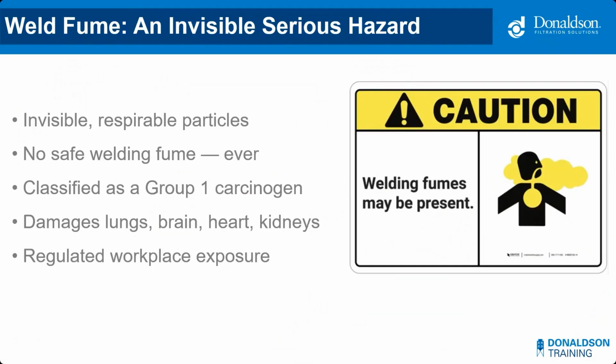Welding fume particles are extremely small, small enough to pass your body's natural defenses and lodge deep in the lungs. Because of that, there's no safe welding fume. Every arc, every process, every day creates hazardous exposure. All welding fumes are classified as group 1 carcinogens, meaning they are known to cause cancer, not suspected, not theoretical. The risk doesn't stop at the lungs. Long-term exposure is linked to neurological damage, heart disease, kidney disease, and blood disorders. That's why welding fume is regulated and why it must always be respected, even when you can't see it.